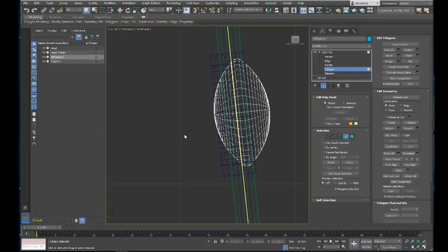We are in the left viewport, and I'm holding the left mouse button down at first because now I'm starting my selection outside of the model. Have you used Photoshop? Okay, so you will use the same method for selecting in Photoshop. I'm holding down the left mouse button and then releasing. And now I just click when I want to mark a point, and I'm creating a lasso. A double click will close the lasso and complete the selection. Okay, just let me click away. Left mouse button held down, releasing. That's my first 2 points.